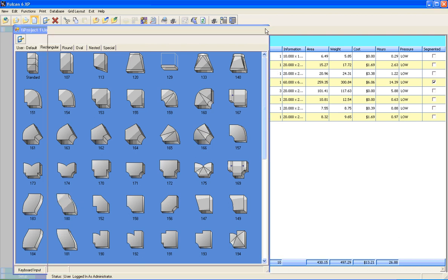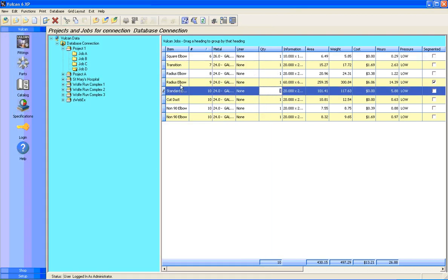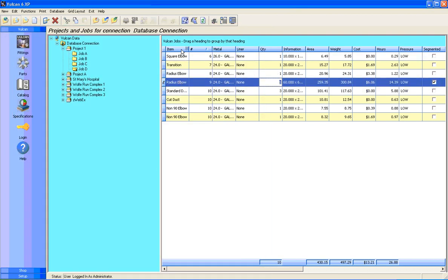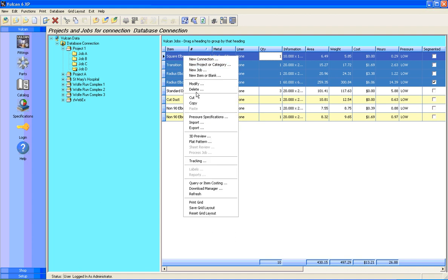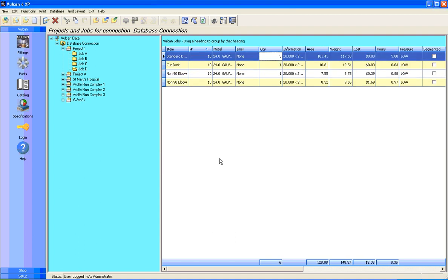And when I go back, I'm just going to delete the previous fittings that we entered. Instead of adding one oversized offset, what it's done is automatically broken that up, as you can see, a quantity of 3 right here, into these 6 separate fittings.